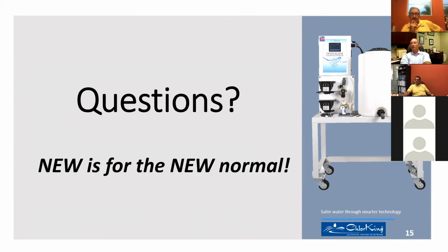So if we've got 1,000 ppm sitting in our holding tank on board, for their holding tank that they want to take out, they only want 200 ppm. So we added a dosatron to that, which auto dilutes the solution. I'm sure you guys are familiar with the dosatron product. That auto dilutes the solution down to 200 ppm in their holding tank. So when they go to use the solution out of their giant 1,000-gallon holding tank, it's already at 200 ppm. It's an easy install.